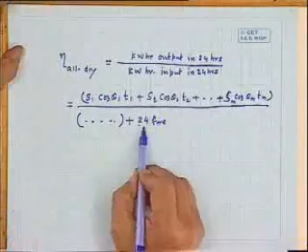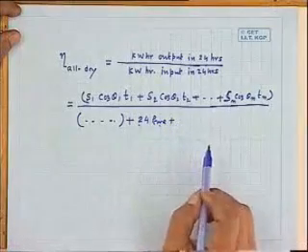Because one should not be under the impression that when the transformer is under no load condition, I will also switch off the supply. That you are not supposed to do, because you do not know, somebody may just go to the hostel now, and want to switch on a light. So the supply authority has to keep the primary energized, no matter whether there is a load on the secondary or not. That I think is very clear. So this core loss is to be supplied 24 hours. So it will be 24 into P core, and all the things in kilowatt.